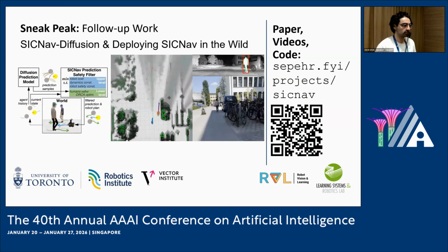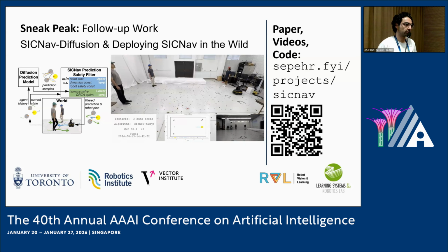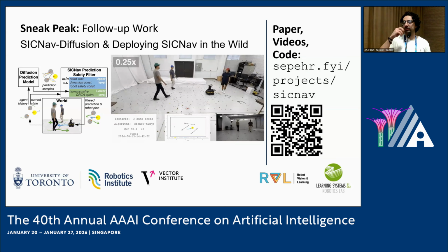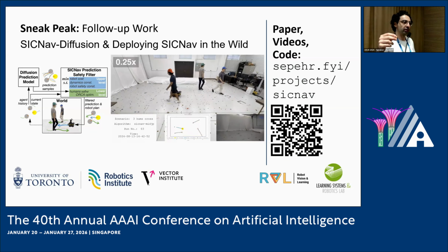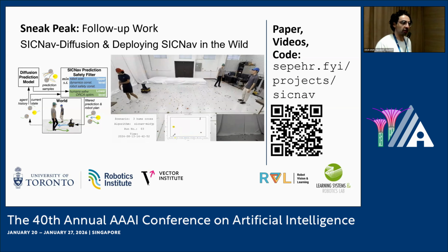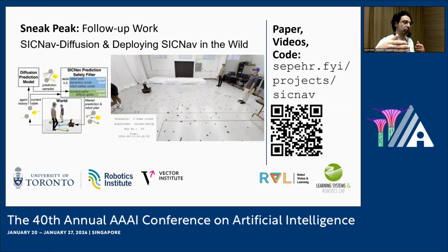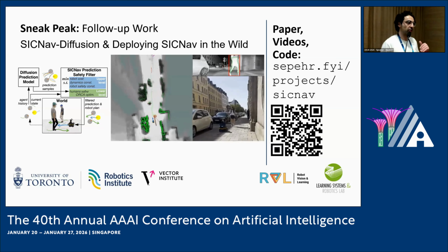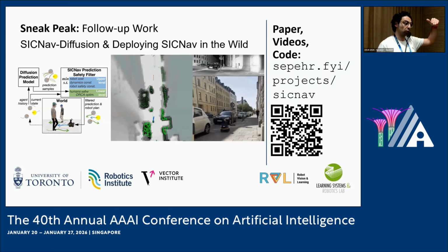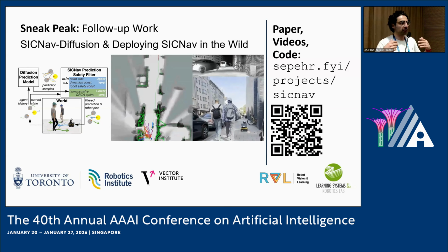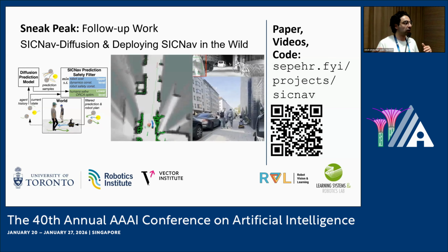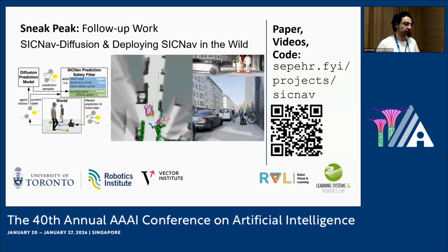Hi. For other dynamic obstacles, like cyclists on the street, would Orca still be a reasonable model to assume? I think what's key about Orca is that it depends on several parameters. The most important are the intended direction the human needs to go, the maximum velocity it can have, and how risk averse it is with respect to avoiding collisions. That affects where the linear constraints for collision avoidance end up being. With different parameterizations, you can end up with a remarkably large number of variations.